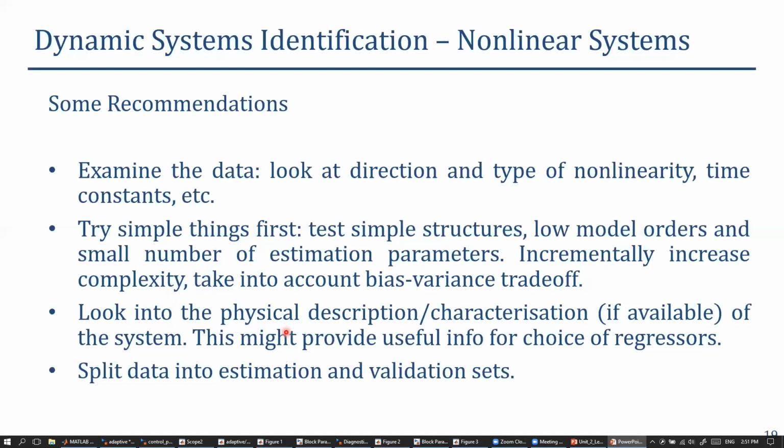Try to look at a physical description and characterization if you can. This actually provides useful information for the choice of the regressors and also the order. Always split the data into estimation and validation data sets. Always.